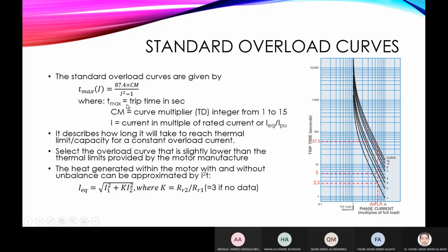Now, this is what the current is: the current measured divided by the equivalent pickup setting. For the current input, some relays use the positive sequence current squared plus the negative sequence current squared times a constant factor, under a square root. This is the current here, divided by the pickup setting.